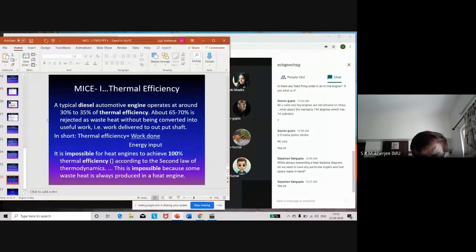And the recoverables are, number one, the turbocharger. You're recovering energy to pump air into the cylinder, which can burn more fuel and give a higher efficiency. Number two, the boilers. Boilers and economizers are the same thing. They are called economizers also. So they are recovering the heat from the exhaust gases to give you hot water, steam, etc.